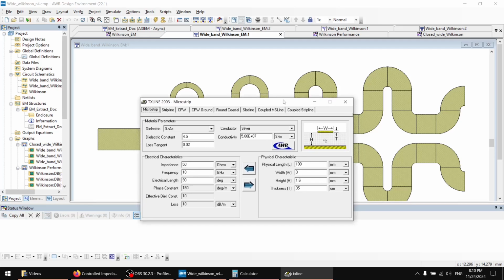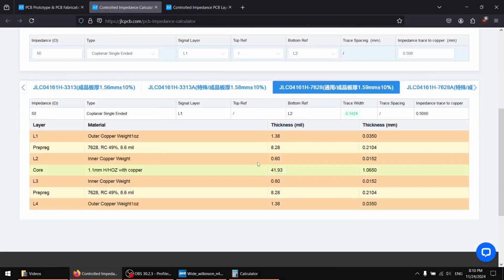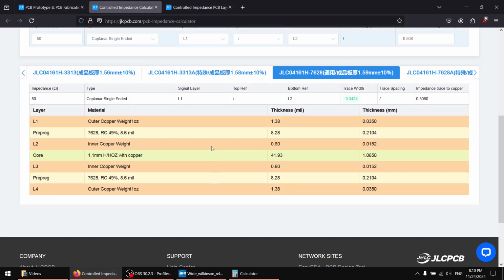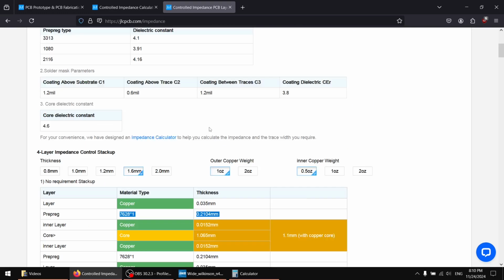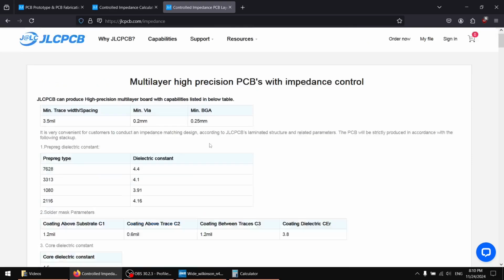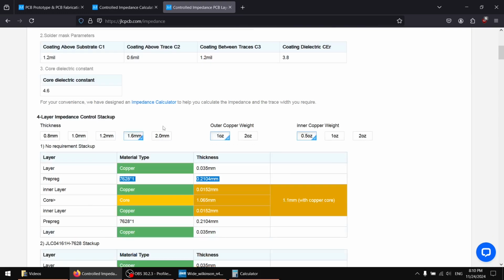Well, it turns out that in a four-layer board, which is often used, for example, in digital design, the layers in between are separated by prepreg, and this prepreg is quite thin. It's only 0.2 millimeters in this case. And what's even more interesting is that its dielectric constant is different from our core, the FR4 material here. Well, there's also the copper layer in between.